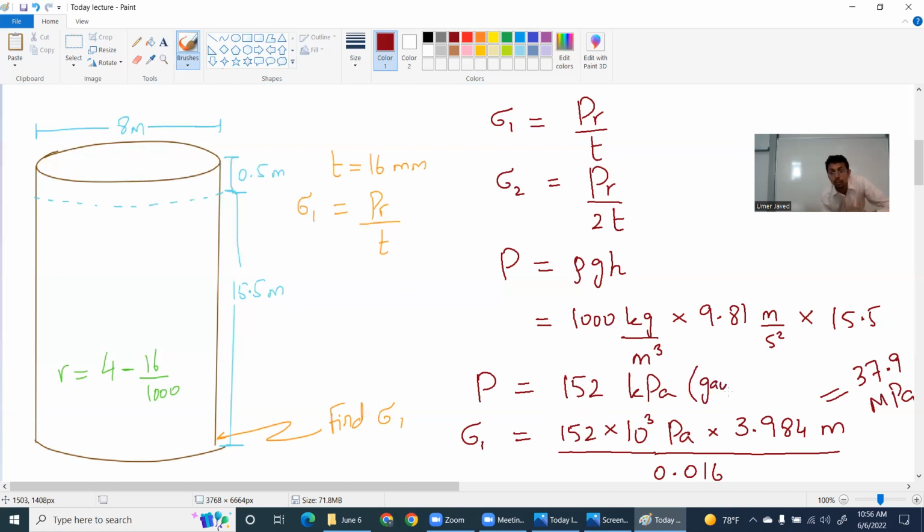And they told me that for using these formulas, you always have to use the gauge pressure. Good. Because at the end of the day, even from the environment outside, there is atmospheric pressure acting, right? So if I have to talk about stresses, I have to talk about the gauge pressure that is sitting inside. So everything is fine, I suppose. You can actually write here "exposed to atmosphere" if you're getting confused. Right here, exposed to environment. So the lid is open, life is beautiful.